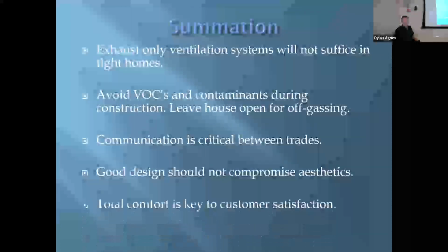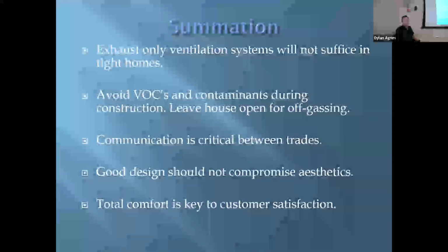So just some final thoughts. Exhaust only systems for fireplace houses, they just won't work. It's going to create too much negative pressure, and so you'll have to do some type of a balanced system. Again, always avoid the VOCs during construction and leave the house open as long as we can, to get off gassing. The communication is something that gets totally missed. Most of the times where this has become a problem, the fireplace guy and the HVAC guy never talked until there was a problem, and now the house is built. Now we're trying to fix it.